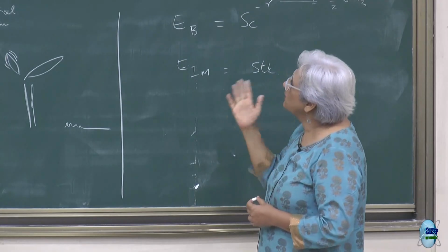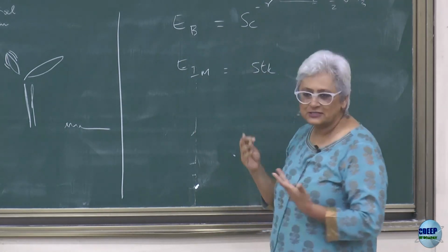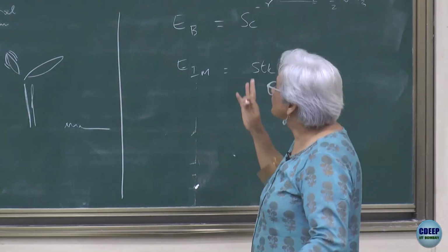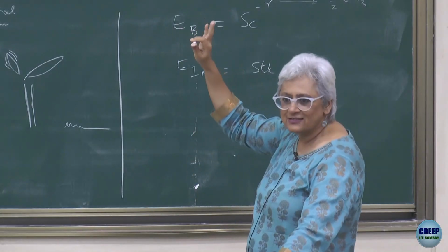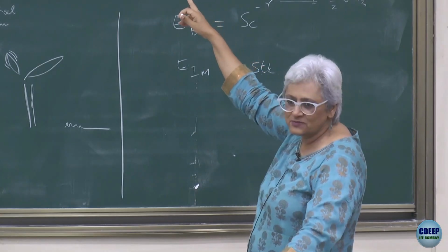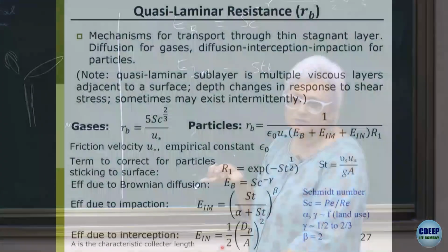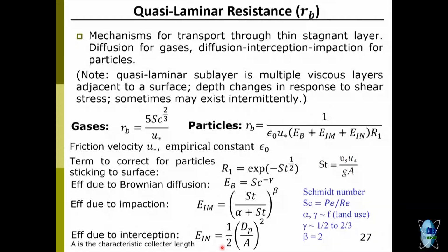And if you go back and look at what each one of those are, you will end up seeing that it is indeed in the Stokes number, because it's written in terms of a Vs, which is in terms of a rho p dp square, etc., and then because that Vs has a g in the numerator, it's divided by a g to get rid of that, and so on and so forth, right? But really, if you put in everything, you'll end up with a Stokes number over there. And in the form that we know Stokes number, you will get it back, right?